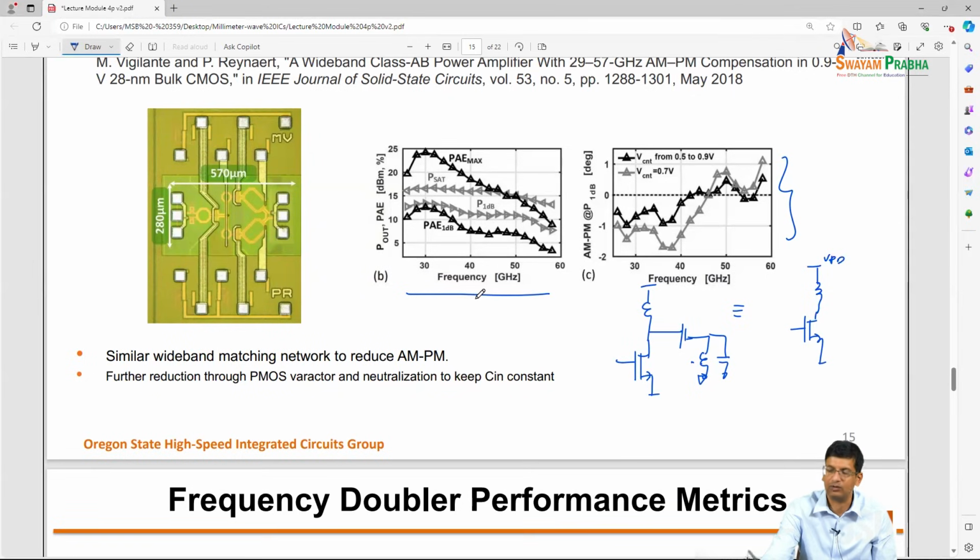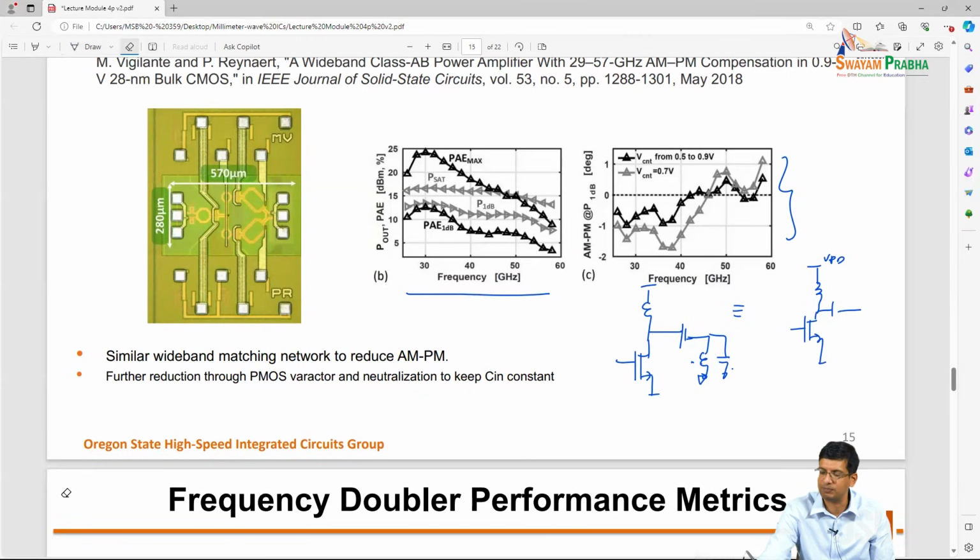The network is still the same. And then maybe I can move this capacitor also. It can be on this side or that side, but putting it on this side helps me absorb the capacitance of the inductor and the capacitance of the device very easily, right? So my network might look like this, and then I have bypass networks to my load.